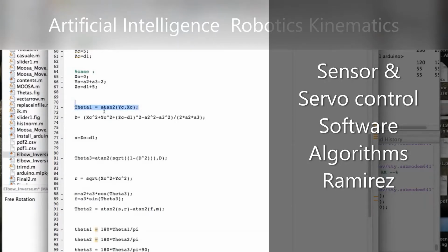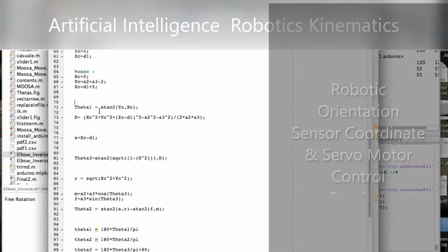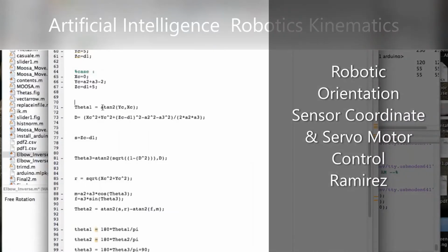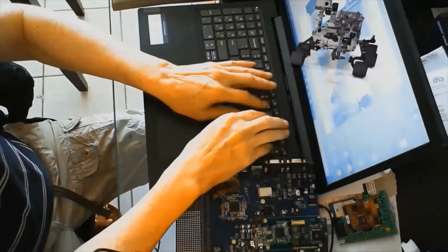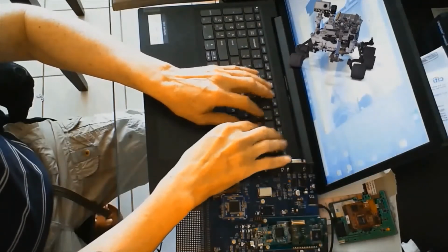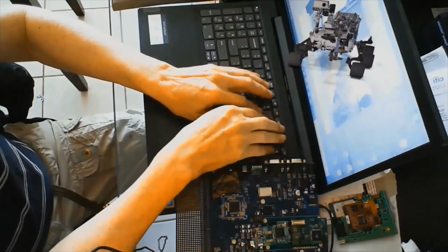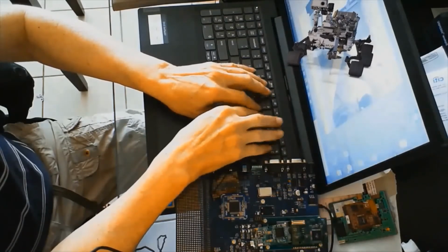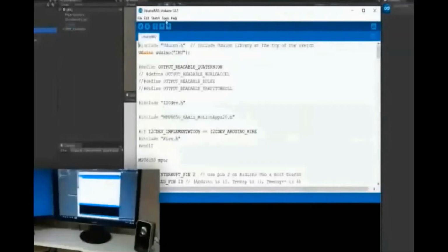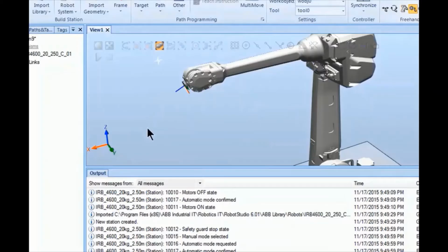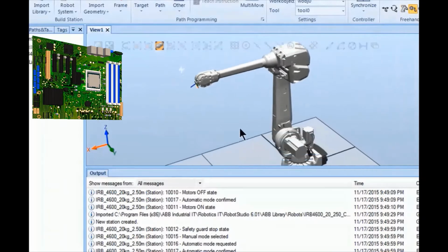The design methodology for the forward and inverse kinematic robotic system. First, moving the hand effector of the robot to a specific location and orientation. Next, calculating the joint angles by the inverse kinematic solution, followed by changing the joint angles to the calculated values.